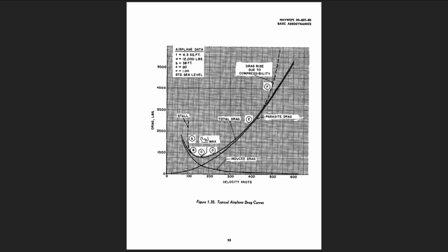One item previously presented related glide performance and lift-to-drag ratio. At the speed of 163 knots, this airplane incurs a total drag of 778 pounds while producing 12,000 pounds of lift. These figures indicate a maximum lift-to-drag ratio of 15.4 and relate a glide ratio of 15.4. In addition, if this airplane were jet-powered, the airplane would achieve maximum endurance at this airspeed for the specified altitude. If this airplane were propeller-powered, the airplane would achieve maximum range at this airspeed for the specified altitude.